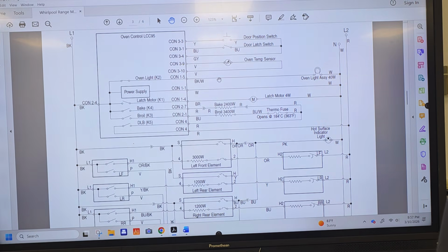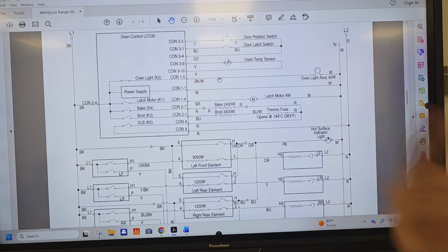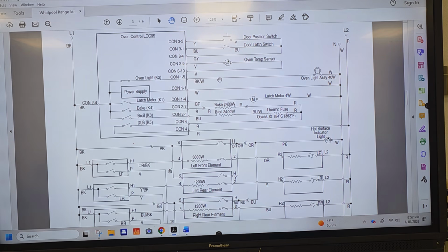The oven we were working on, the decor. Don't tell me about that stupid fan we're dealing with, but go ahead. Well, it's going to relate to it. The sensor checks out with ohms, the elements, both bake and broil, check out with ohms on both lower and upper. All the relays for the bake, the broil, and convection on both lower and upper are working. Mm-hmm. And what would your final diagnosis be, other than that fan? No, the reason why it's showing the error code for the oven temperature sensor.